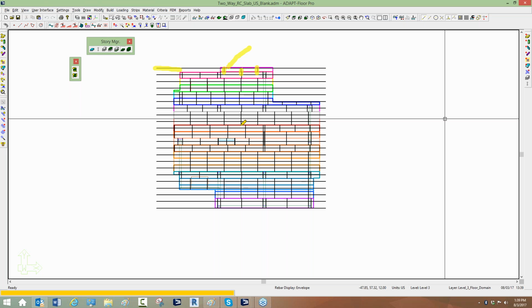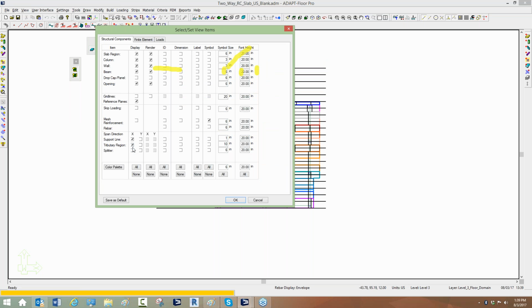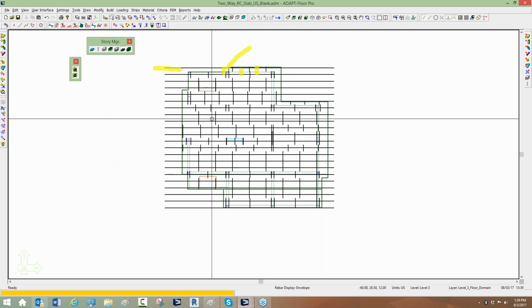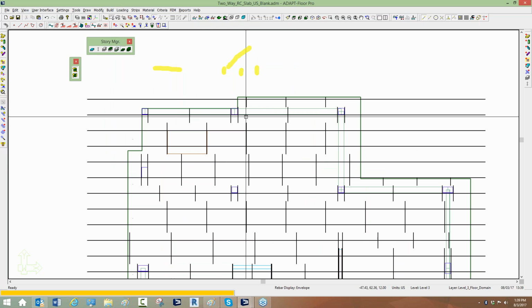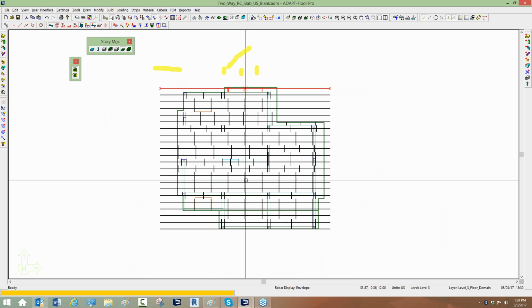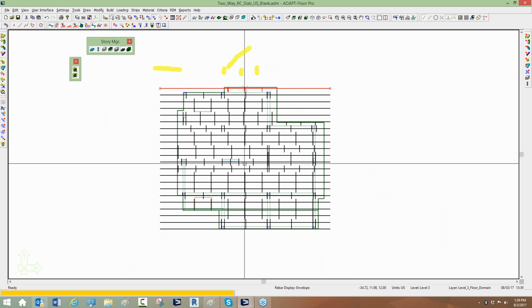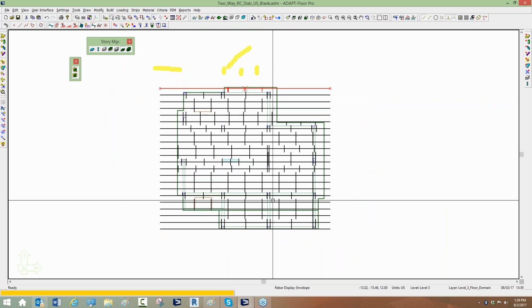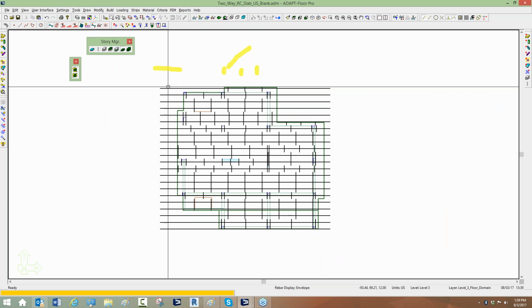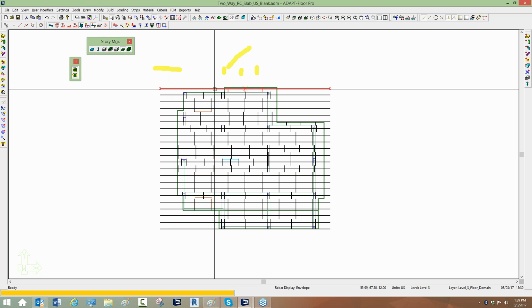There's not many design cuts. And so if I go back to blue eyeglasses, I'm going to boil this down to only showing the support line with the design cuts. And you can see that this just is not uniform enough. It seems almost random in where the program is taking the design cuts. And the reason it's doing this is because the program defines the number of design cuts based on the span.